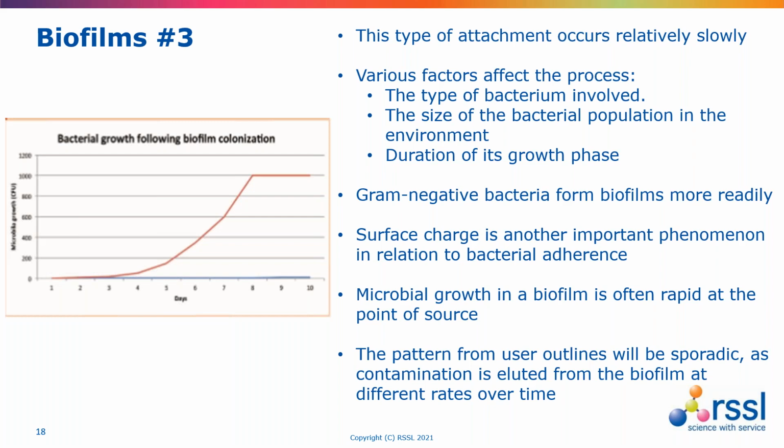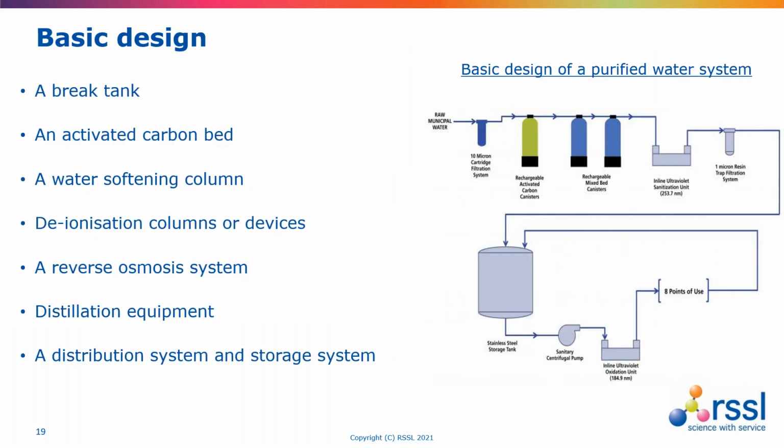It's also an irony that many stages of the water purification process can create conditions which promote biofilm formation, because as we purify the water we create niches of low nutrient richness. Those organisms that can survive then tend to become the hardiest organisms, which are those most predisposed to trigger biofilm formation.